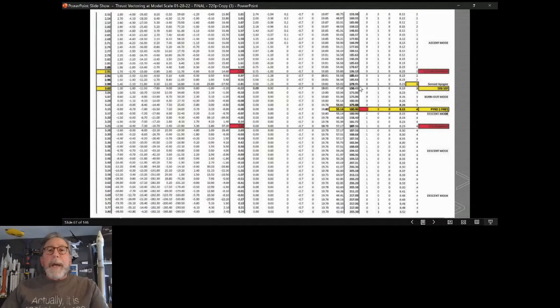I couldn't figure out why the pyro was firing a little early, the parachute deployment pyro. Well, it turned out that it was changing modes and going into burnout mode. This only happened when I started using a larger E12 in the SRB, but it was thinking that the core motor had burned out. So it went into burnout mode and then fired the parachute. So that wasn't what I wanted. I wanted the burnout of the core motor to be what deploys the parachute. So it was a pretty simple fix.